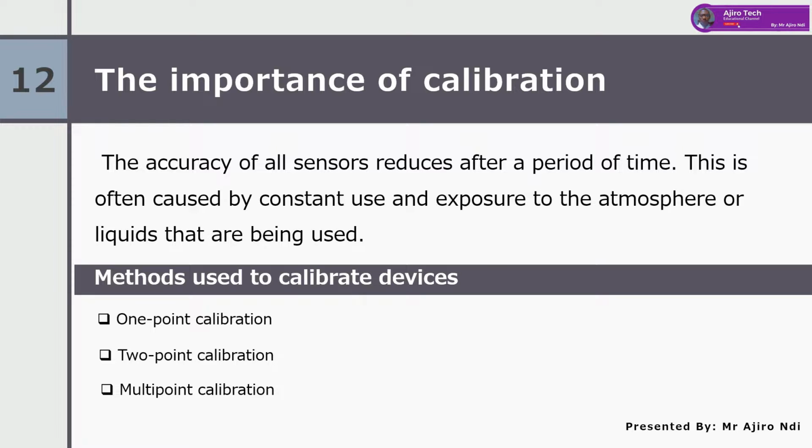Let's take a look at how to calibrate a temperature sensor as an example. In order to calibrate the sensor, there needs to be some way of creating a known temperature. This can be done by using a heat source that generates an accurate temperature, or a mixture of ice and water which can give an accurate reading for 0 degrees Celsius. The sensor, when activated, generates a voltage which is converted into a temperature reading. Now, the algorithm to do this can be refined so that the temperature reading matches the actual temperature.